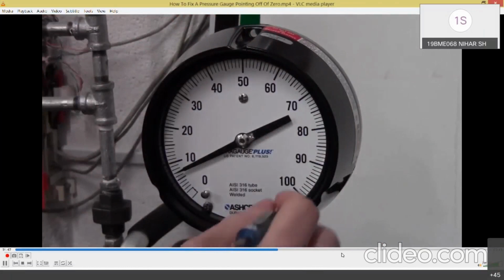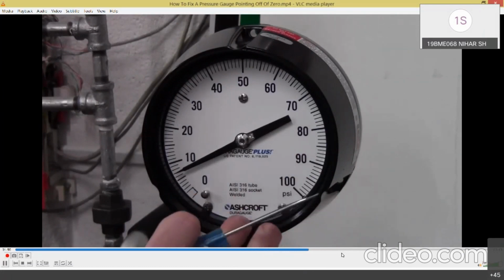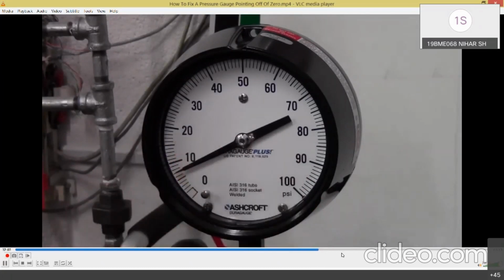And you may see a black elastomer and O-ring on the inside. That's utilized to keep dust from getting in, and if you have a gauge that's liquid filled, which this one is not, it'll help keep the fluid from staying in as well. We can ignore that in this case since it's dry. We don't need to touch that. We have access to the inside of the gauge anyways, and we can get moving.